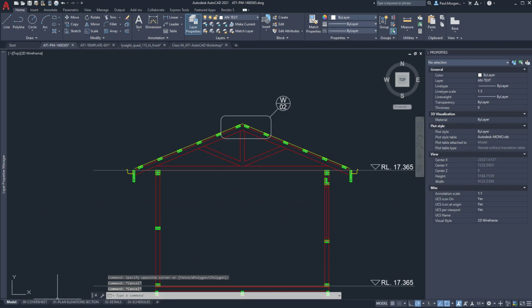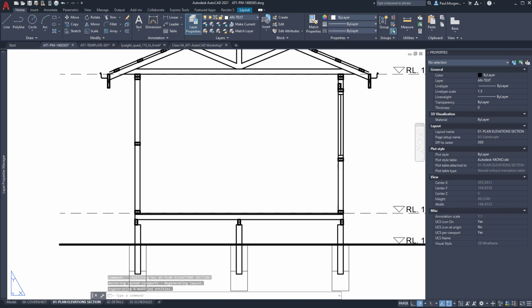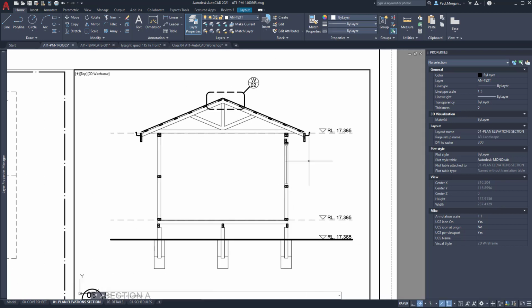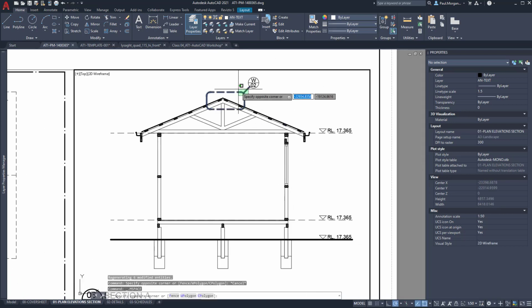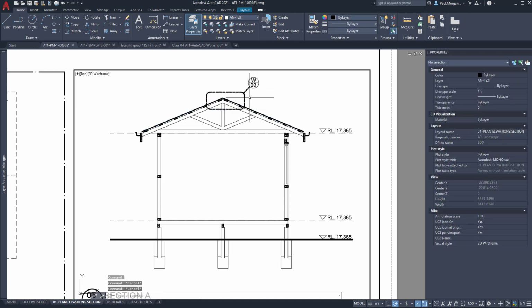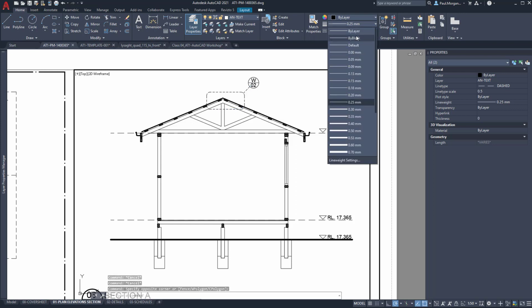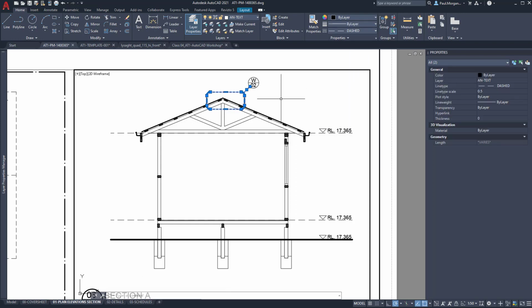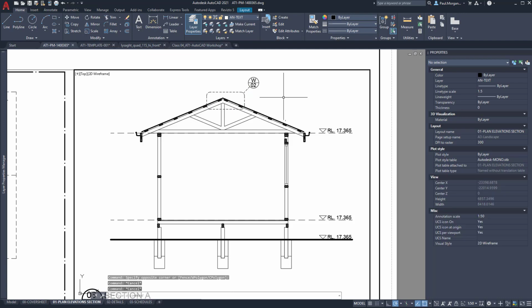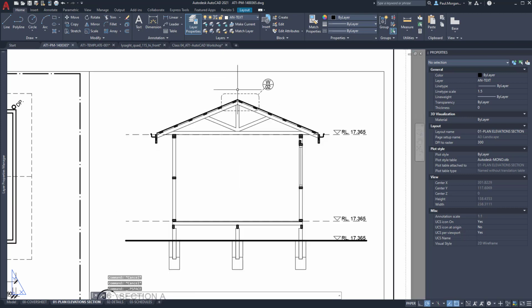So let's go back into our paper space and edit accordingly. Okay, so we've got something that looks like this. I'm going to zoom into the area and then double click to activate that viewport. I'm going to click on these two lines, and under the line type scale, I'm going to change this to, say, 0.5 and then enter. And you can see those dashed lines are closer together, but I definitely don't like the line thickness. So I'm going to change this back to by layer. Something like that. Hit escape a couple times, and we're done. Double click out, and that's how you draw callouts.